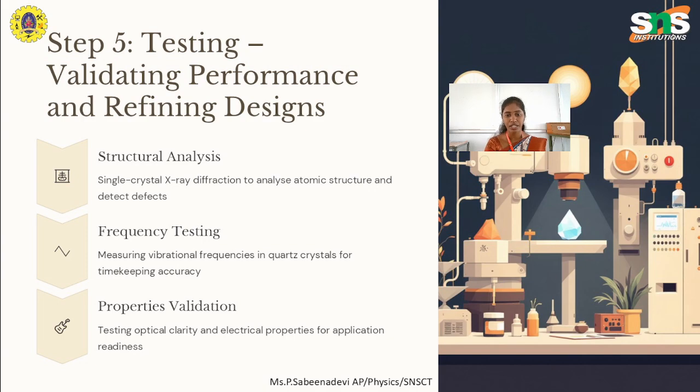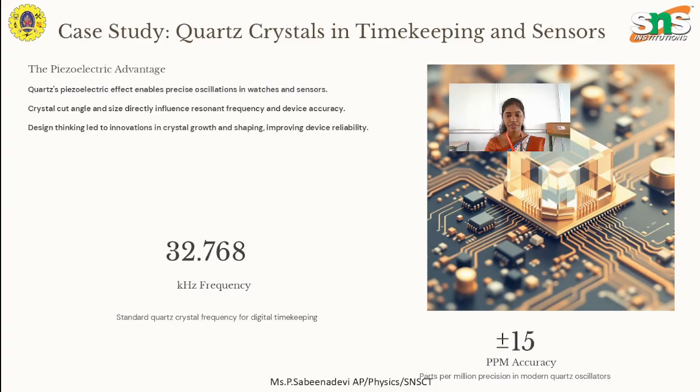Next is testing, validating performance and refining the designs. First, structural analysis: single crystal X-ray diffraction to analyze the atomic structure and detect defects. Next, frequency testing: measuring the vibrational frequency in quartz crystal for timekeeping accuracy. Then properties validation: testing optical clarity and electrical properties for application readiness. These are all the testing part.